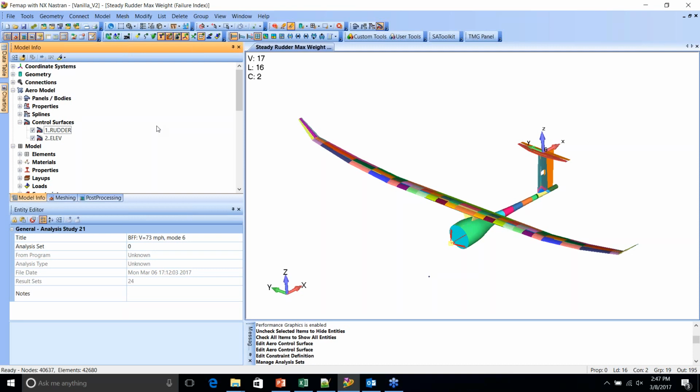So you can knock it down by 50% or 80%, whatever you think, so you can sweep over a range of effectiveness values. That way you're considering that kind of behavior, because that is important when you're talking about control surface flutter. So thank you, Sam, for mentioning that.